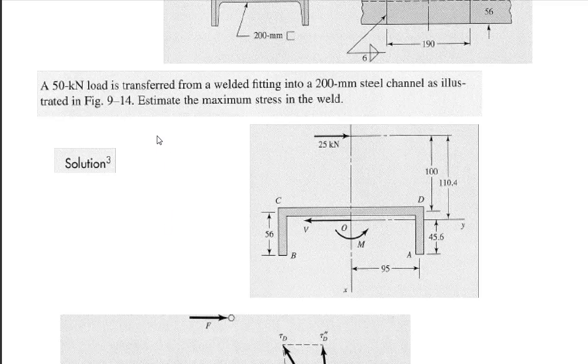And what we have is, again, this shape. We need to calculate its area, its centroid, and its polar moment of inertia. Now notice the loading up here that is offset in the horizontal direction. That loading can be replaced by a direct shear of the same size and the moment that it produces. The direct shear will create primary shear stresses in the weld, the same everywhere, same direction. It's just going to be a force over area. But this moment is going to create secondary shear stresses that at every key point within the weld will look very much like the bolt secondary shear stresses.